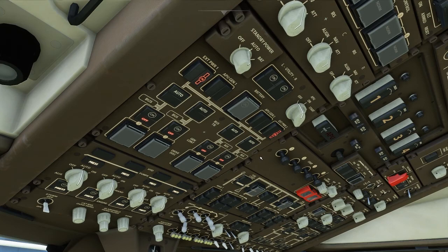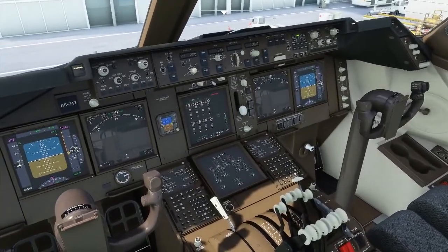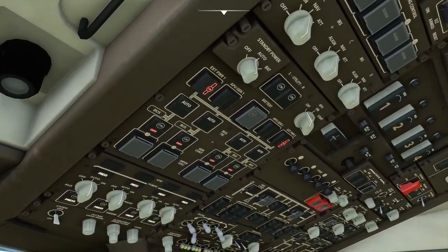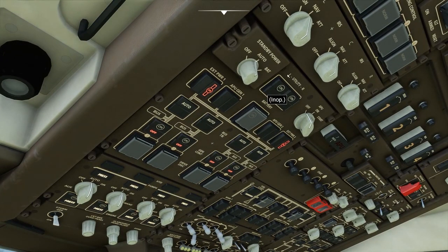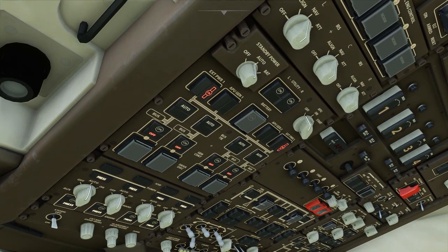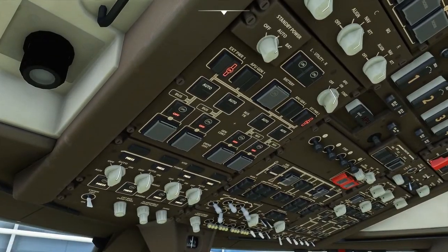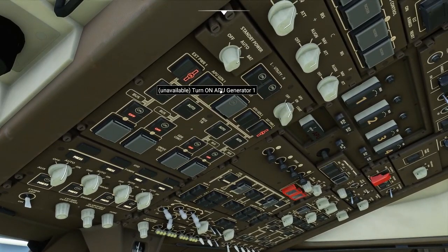You know, all your circulation and your air conditioning kicks on, so the aircraft basically springs into life whenever you do that. And most importantly, you would have your utility power on left and right, which is an option in this, but that means that you get power to your galleys, so your cabin crew can start making you a cup of tea. So that's basically the aircraft powered up.